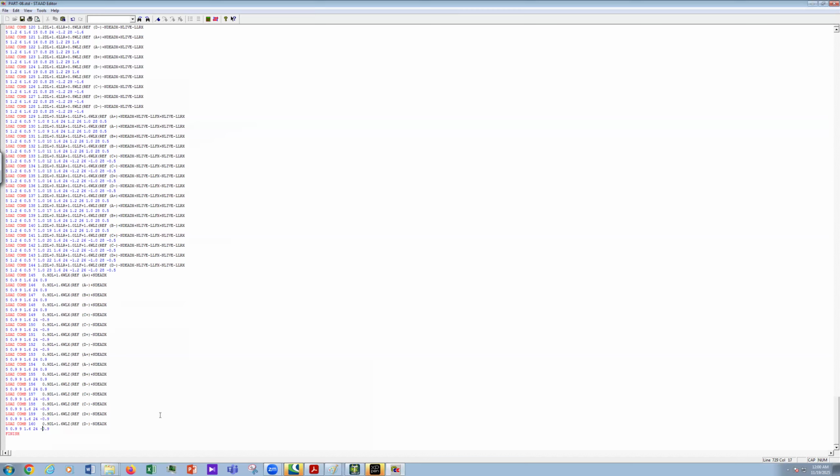So you can see our load combination has been prepared. This is a shortcut method and an easy way. If you are good at edit file, this will take less time than the previous method. You can apply this method for the previous load combinations too, but be careful with the number, with the name, and with the minus sign, and the directions.